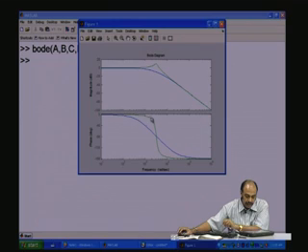This is a much better filter compared to the earlier one, it falls much more sharply in phase to 180 degrees. So, it is not a gradual change to 180 degrees, but magnitude filtering wise they are more or less the same, because they are going to have the same minus 40 dB per decade, but phase wise it is going to jump quite fast to 180 degrees.